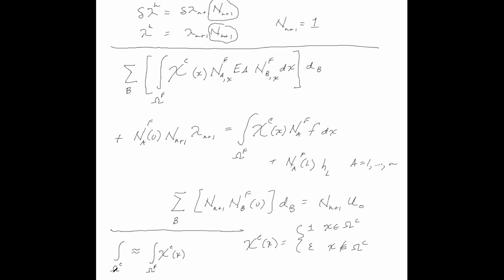So I've replaced integrals over the actual CAD domain with integrals over the flex domain, and I'm using an indicator function to determine which points are inside or outside the CAD domain.